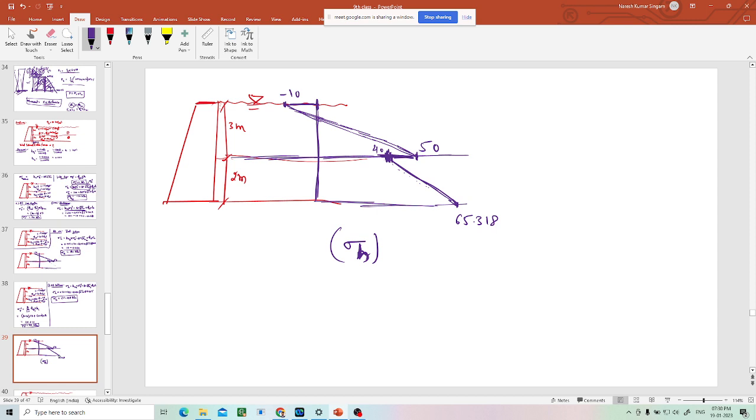So what else can we do now here? You have to find out the total force in the horizontal direction. How will you do it? See, this is the negative diagram. This is the positive diagram, right? You can calculate the effective force. That means you have to calculate this force, then you can deduct this much force from this positive force. That's it, it's like summation. Suppose sometimes people may ask, you can neglect the tension zone. So what is tension? What is compression? I'll tell you now here.